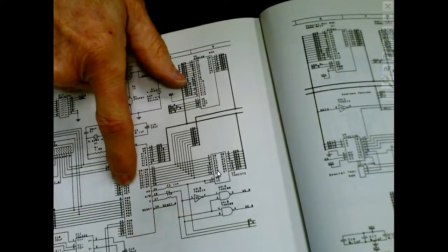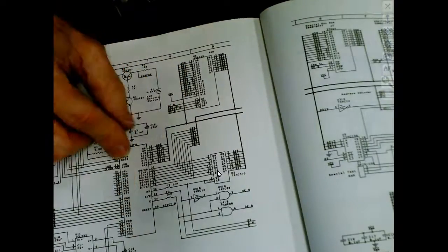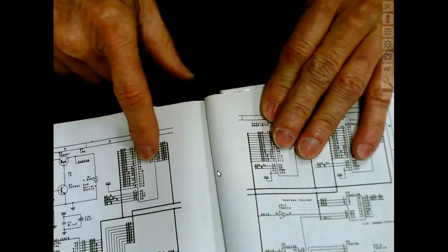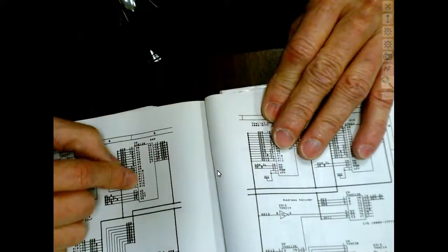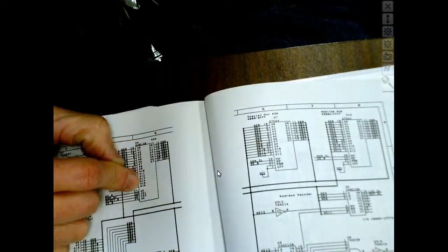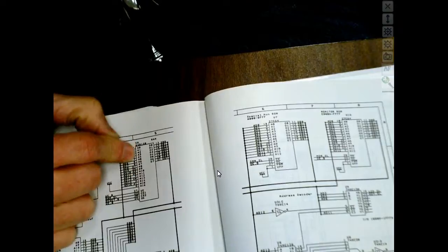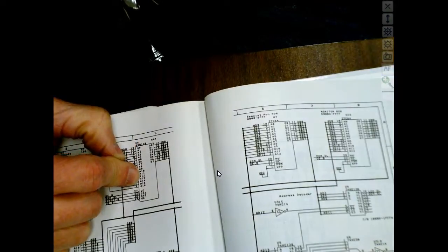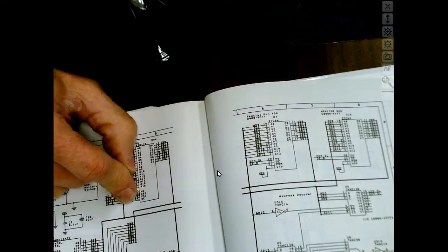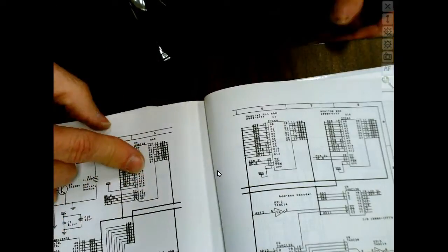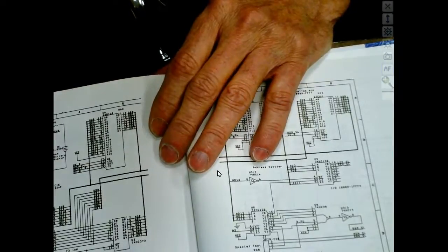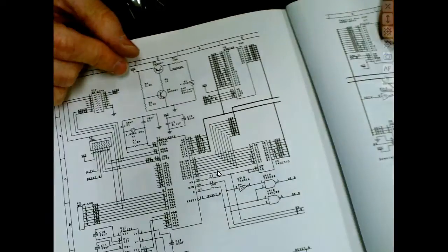That's what the P stands for. So these are I/O ports. You don't see the address buses that we looked at. 62128, this is a RAM chip right here. And you can see all the address lines where we actually select locations. Here's the data lines. This is the data bus we talked about. This is the address bus that we talked about. I remember that when we gave you the brief layout of a computer. Here's the control bus right here. This is control. And so this is RAM right here. This is ROM. What else? This is an RS-232 interface right here.